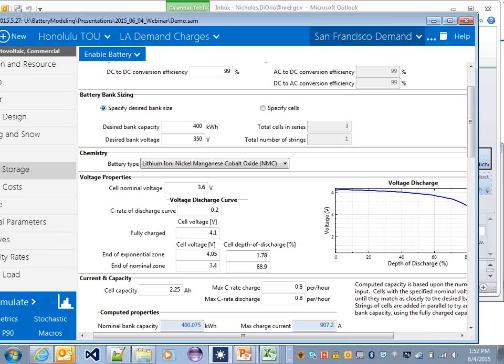But for the moment, we've chosen not to add it to PVWatts. So that would be something we could also do. Is that the model that you primarily use? Typically, if I'm just screening a site, I don't bother trying to figure out what model panel it might be or how it's all wired up. In that case, you can just enter a 4 or 5 kilowatt size, and the default panel will give you close enough.